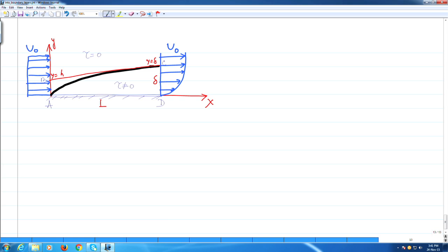I am drawing the control volume in such a way that it encompasses the part of the flow where the viscosity effects are present, which in our case is the existence of the boundary layer. So I am cutting it off exactly there, using a streamline which best defines that.